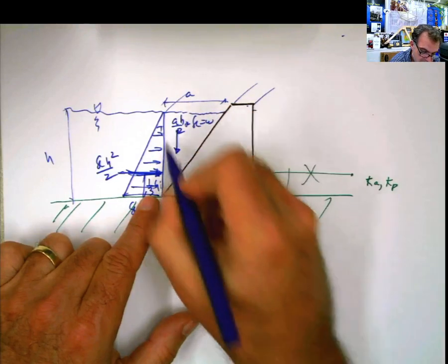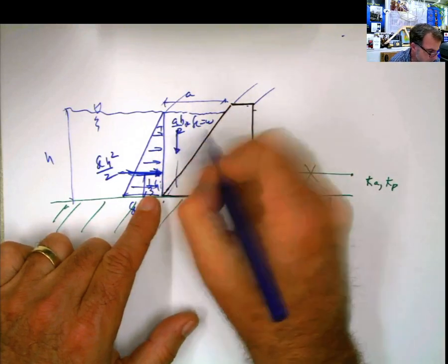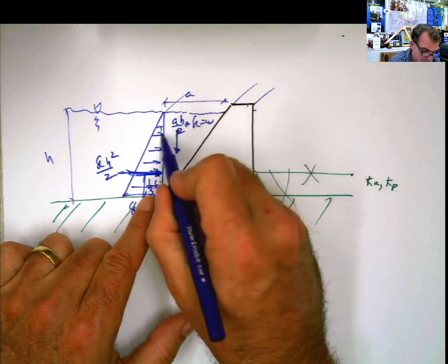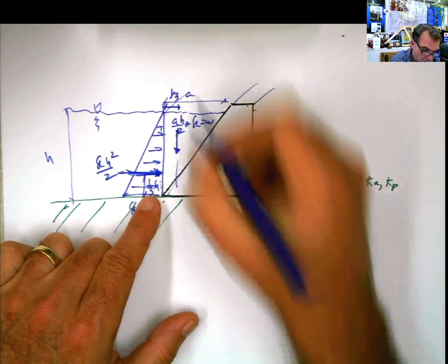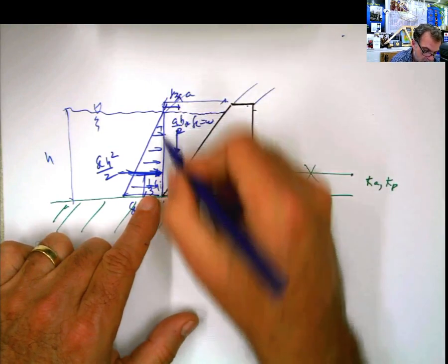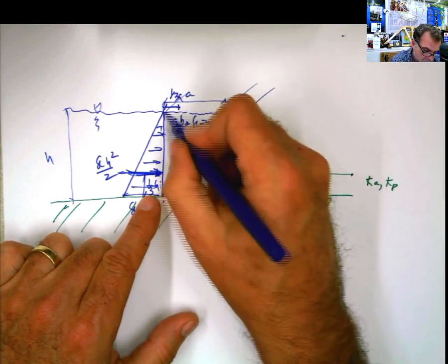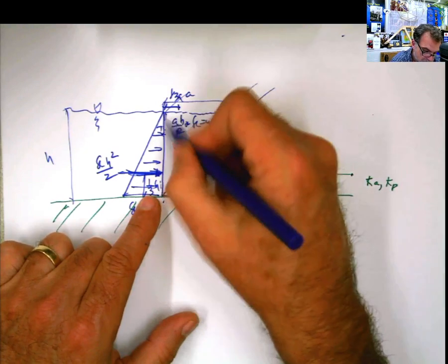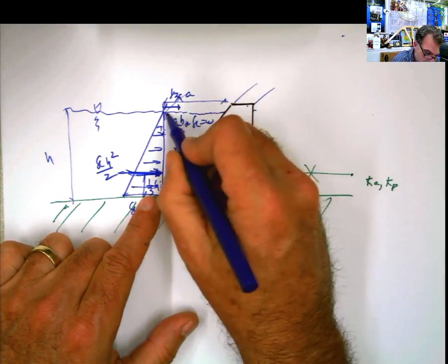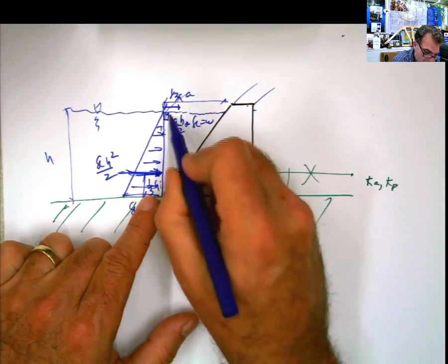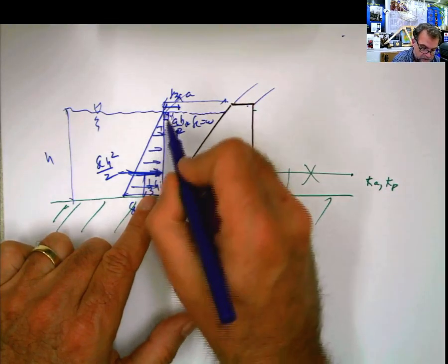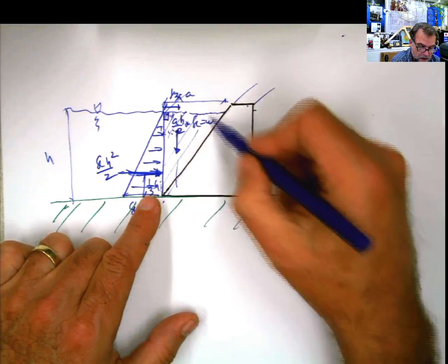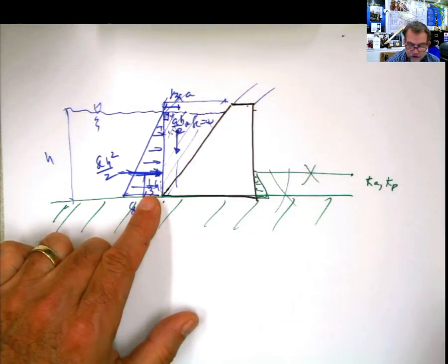And the weight of that block is going to be acting here, on top of this, right? It's going to be acting there. And what is this? This is 1/3 of A, and this is 2/3, because this is the right angle that I'm studying, 1/3 of H in this part for this block. Now you have those two forces. What other forces do you have?